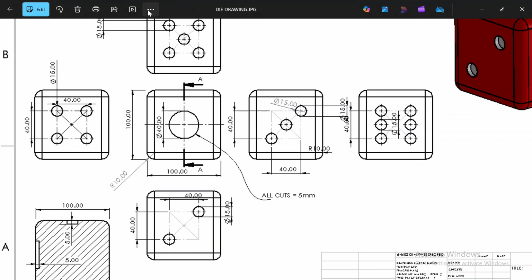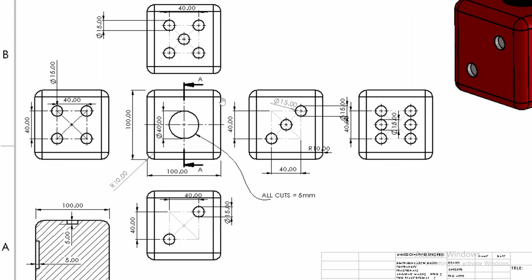First, we're going to extrude the cube out, and then we'll fillet the edges. That's it. The radius of the fillet is 10. The length and width of the square is 100, and the dimensions for the numbers have been given to us. We'll talk about them as we go on.